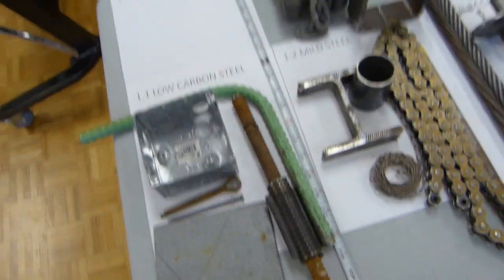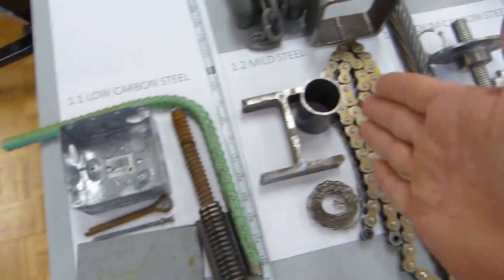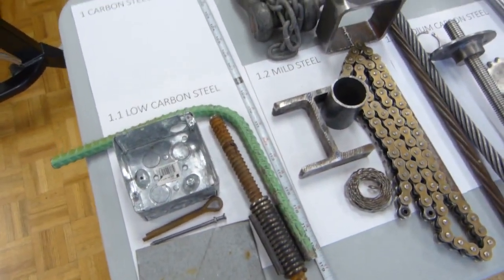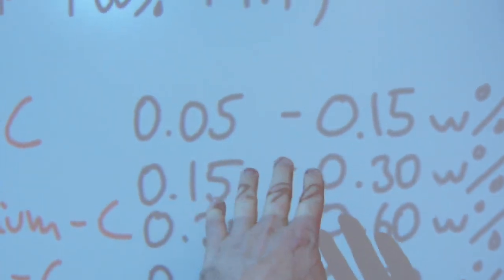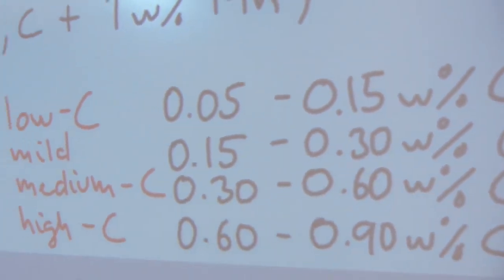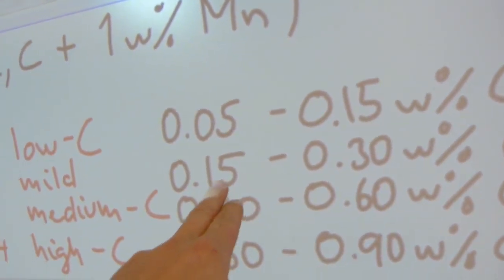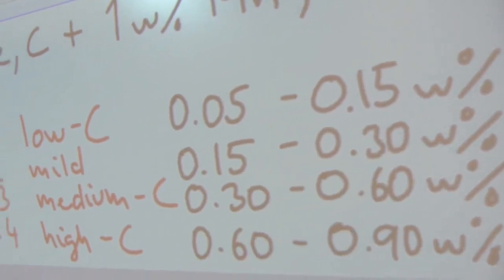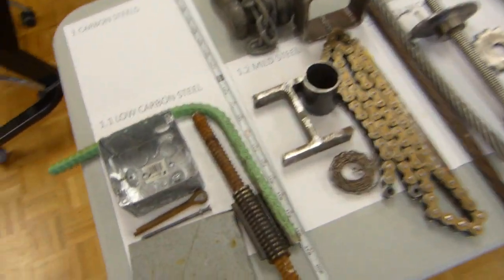The next group is mild steels. They are stronger than these ones as they have more carbon in them. Not a whole lot more carbon. If we go back to the table here, how much more carbon? There, those are the numbers that we had. So we are here at mild carbon: a little more than 1/10%, 2/10%, or 3/10% carbon, and that difference makes a lot of difference.